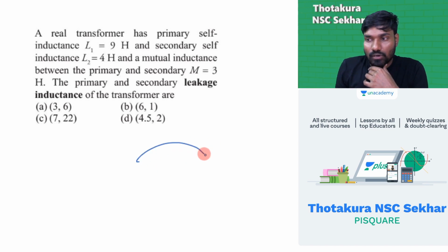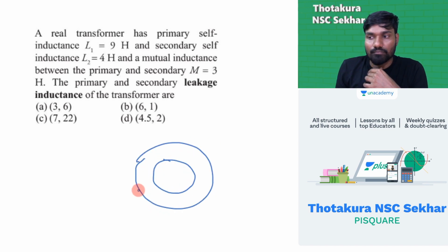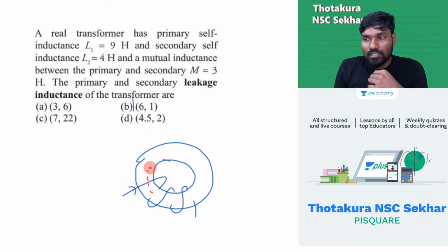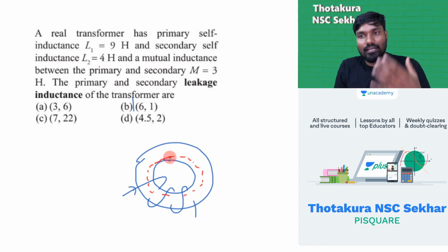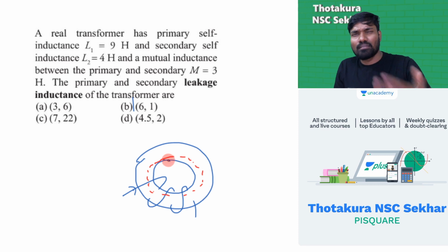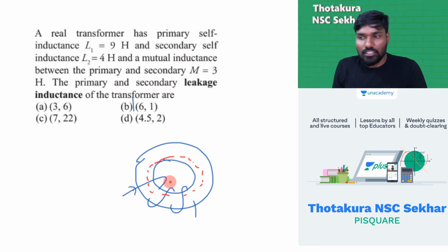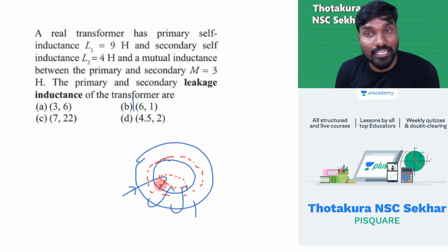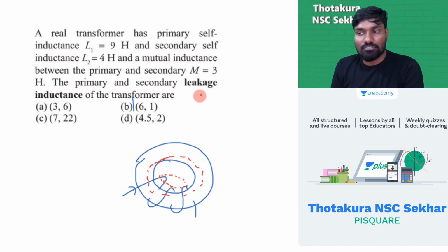So if I have a core like this and a coil like this, I'm just giving an example. I'm thinking flux should go this way, because this is a magnetic path, which has better magnetic conductivity than air. A little better, maybe 10 times better. So there is some magnetic flux that comes this way also, because air is also conductive. That's what we'll call the leakage flux.